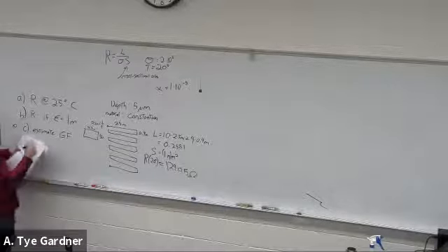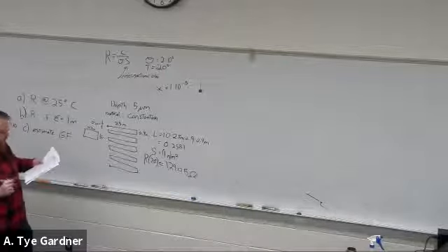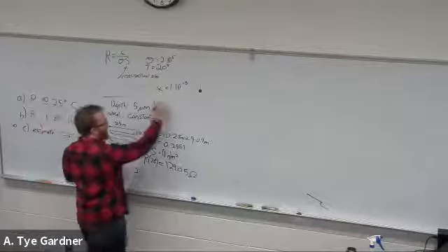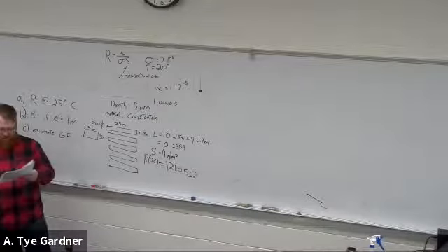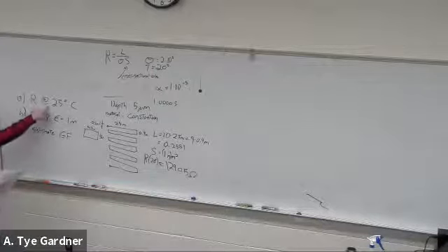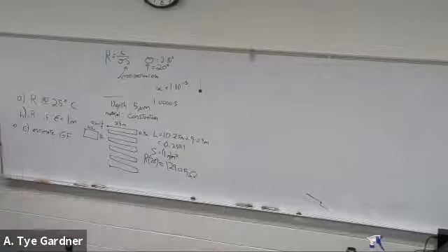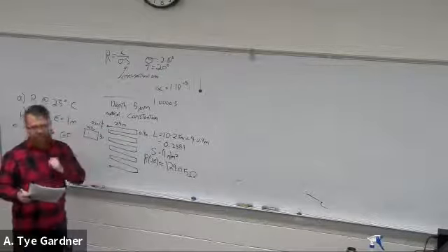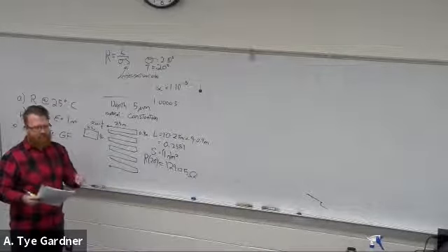This is actually kind of funny, because if you have any sort of sig fig tracking, your multiplication factor is 1.5, which means that your resistance at 25 degrees Celsius is the same as your resistance at 20. So for Constantan, it has a very low temperature coefficient, a very small change in resistance due to temperature.